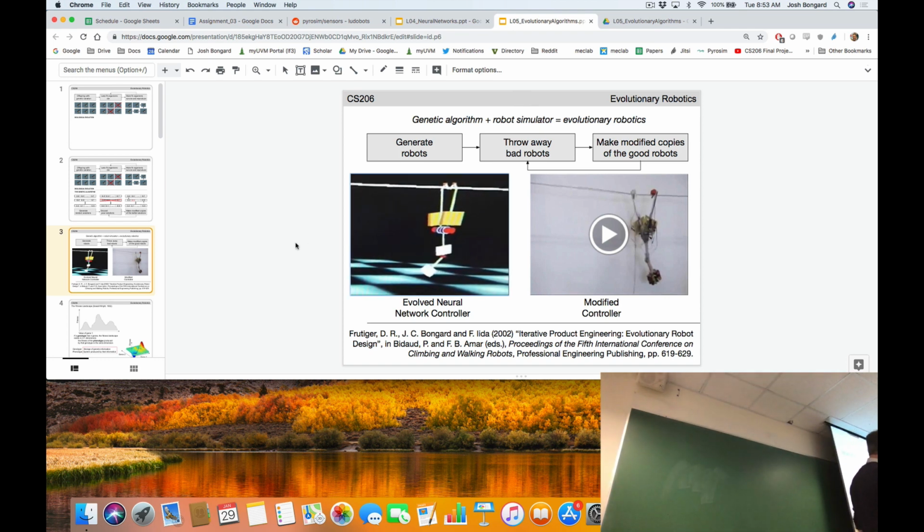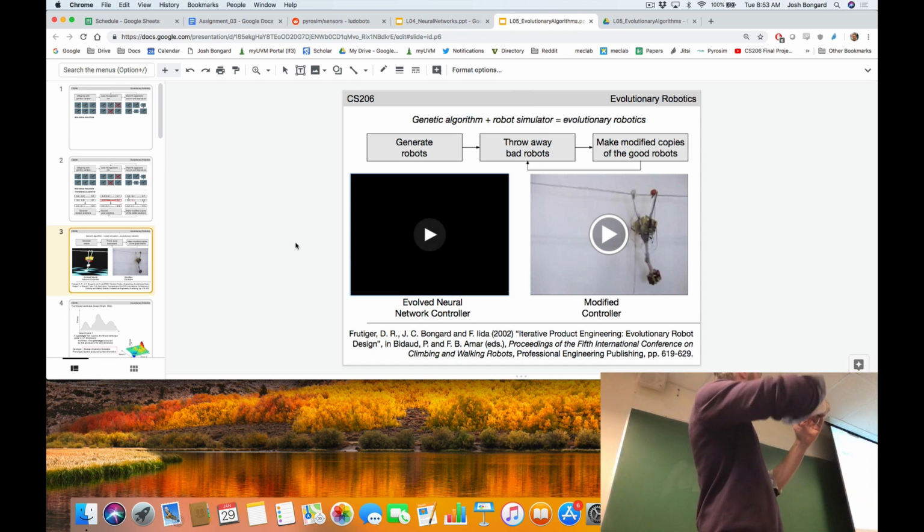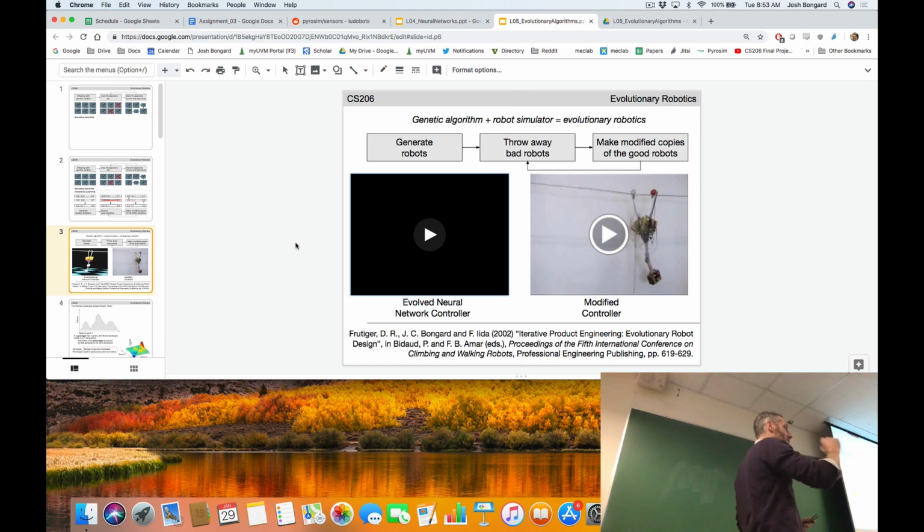We put it towards the bottom of the robot, and if you watch carefully, you'll notice that the lifting of the hand and the placing of the hand is timed to the swing of the battery pack. So as the battery pack swings forward, temporarily the entire weight of the robot is lessened because the battery pack is rotating upwards. And when its weight is lessened, it's easier for it to lift its arm and place it a little bit further along the bar.